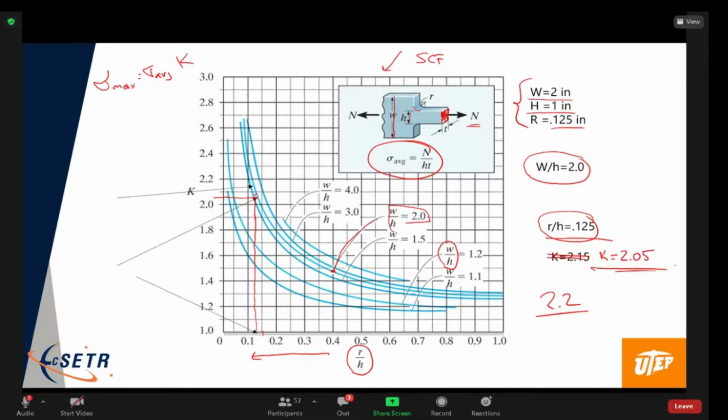And what they found is when they took these ships out into the North Atlantic, they fractured in a massive way. They fractured as if it were a toy boat and you just snapped it in half. And the reason was partly that the steel became brittle in the cold weather, but they never took into account the fact that they had all the rivet holes.